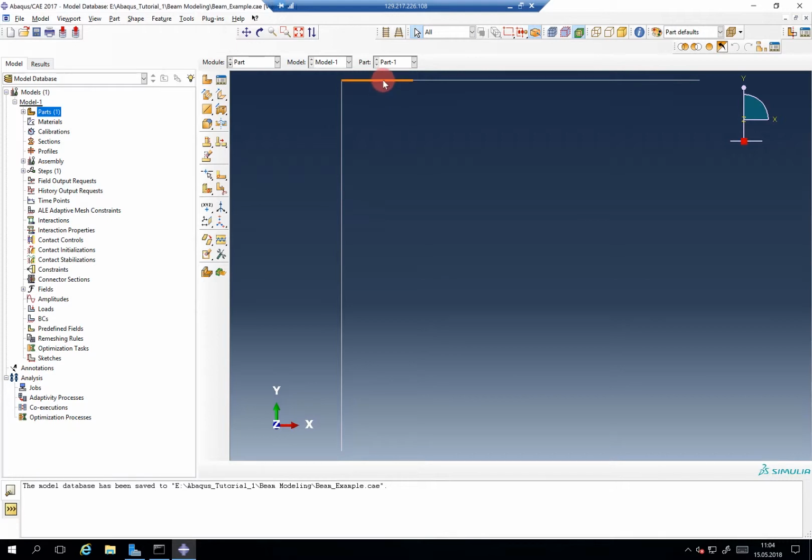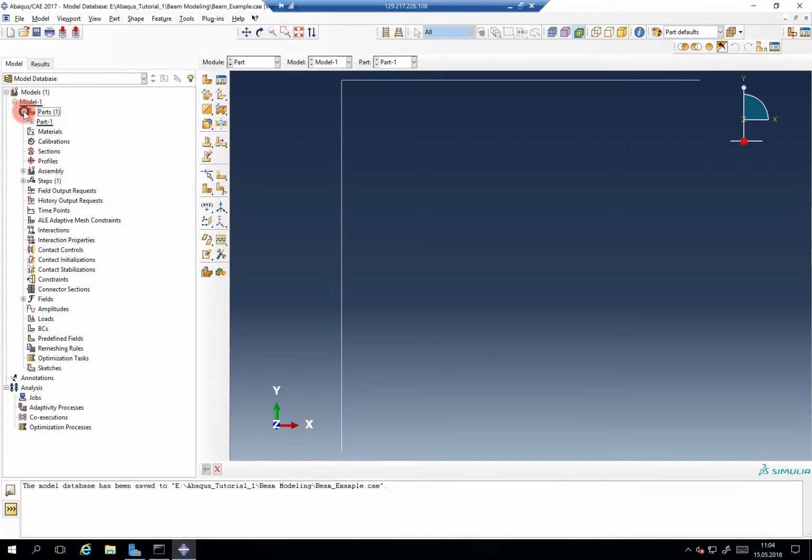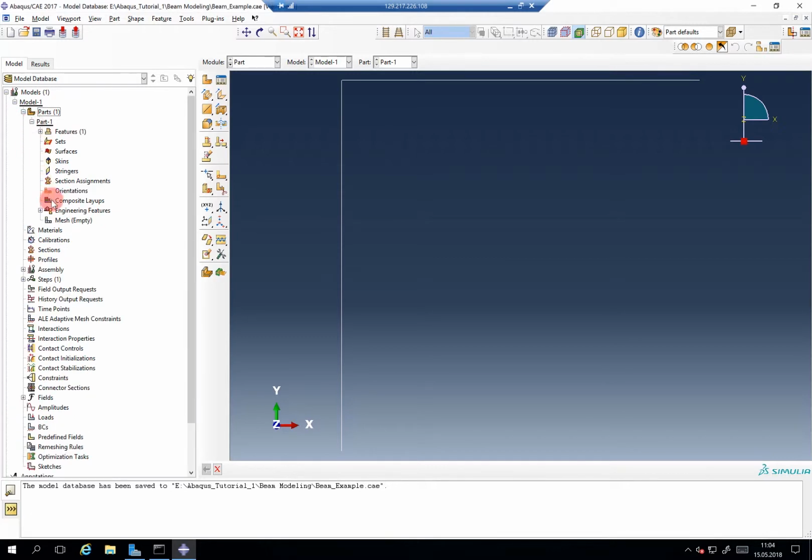That is our sketch. Now you can see if I hover the mouse over the respective parts, the entire thing is considered one beam. However, this is a section of it. Okay, now this is also confusing, but a feature section. So at this point, which is now highlighted, we could apply a boundary condition. We've talked about this before. So now let's mesh the part.